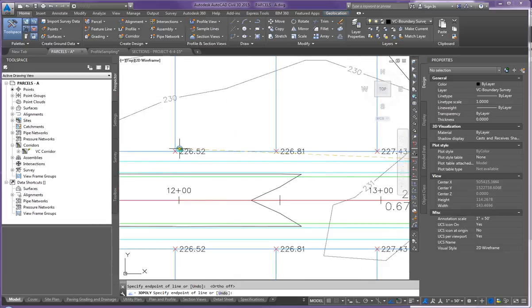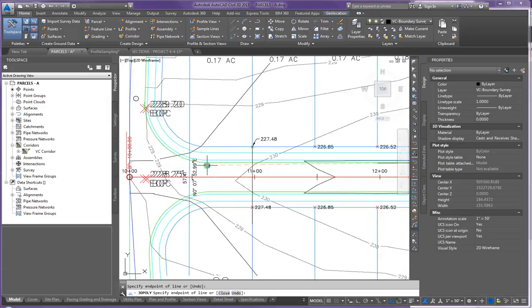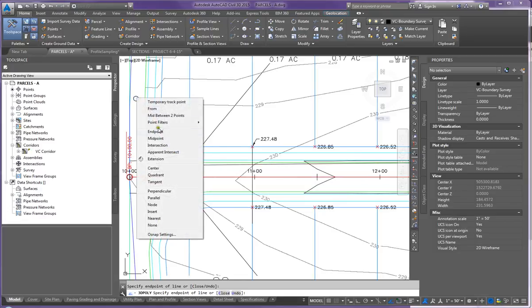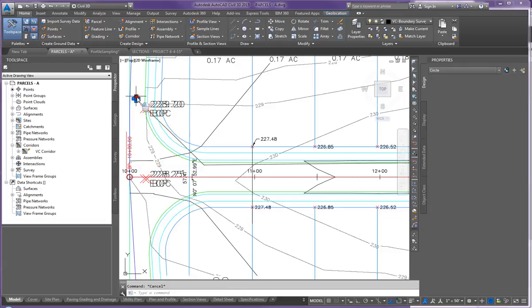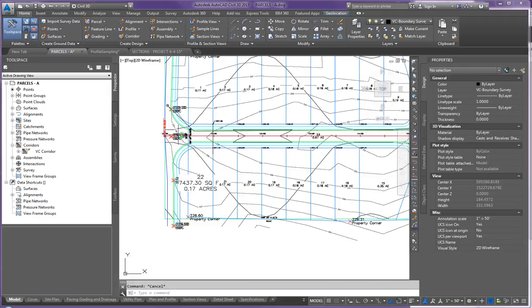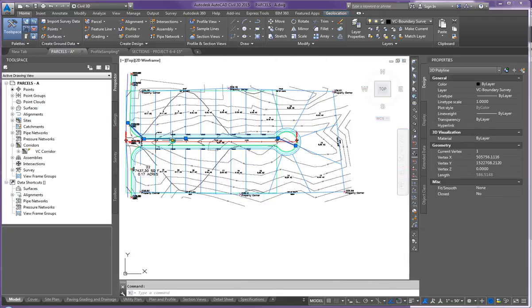And I know the low point I want is going to be at this property line, and I'm going to have to put another low point down here, and then I'm going to tie into this existing location. We're going to assume this is an existing storm location. All right? Now, what I've created is a 3D polyline.